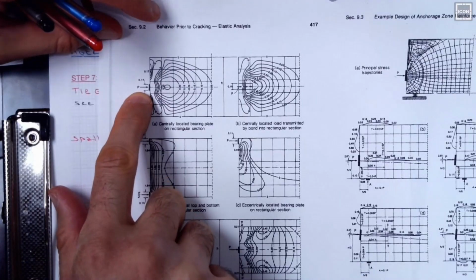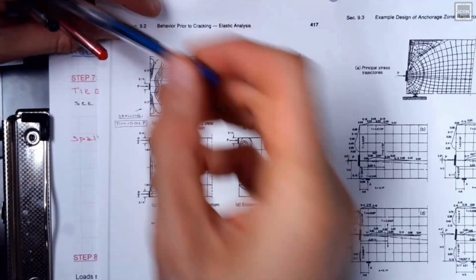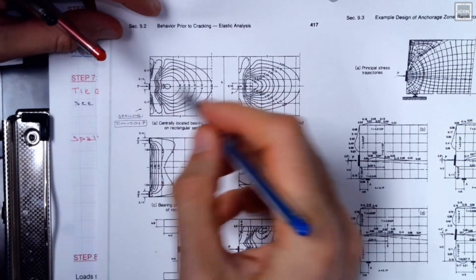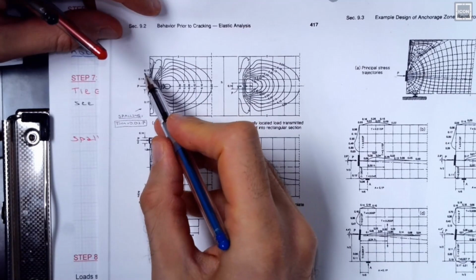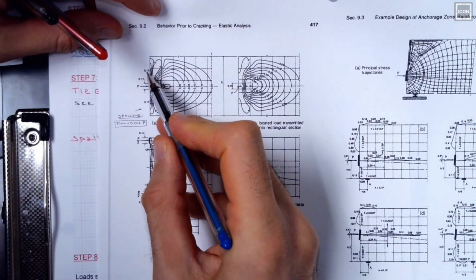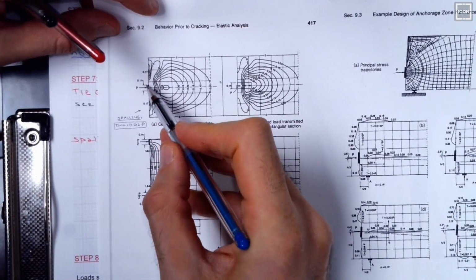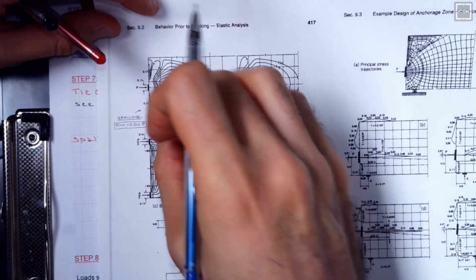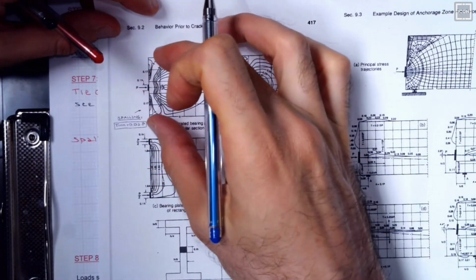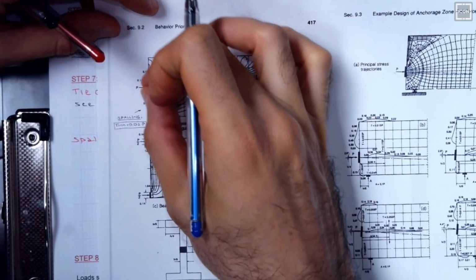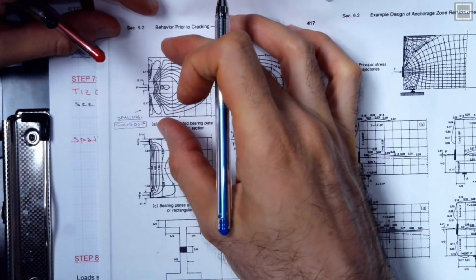There is a significant force applied and you might have spalling at the top surface, and this is coming from elastic stress analysis, and you can see 0.17, which is 17%. Of course, it depends on the proportions, how narrow the plate as compared to the section, or how wide the plate as compared to the section.